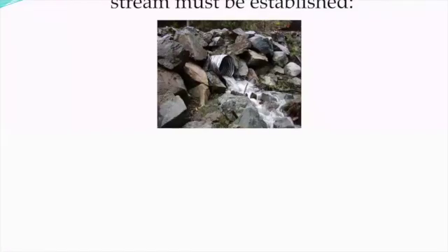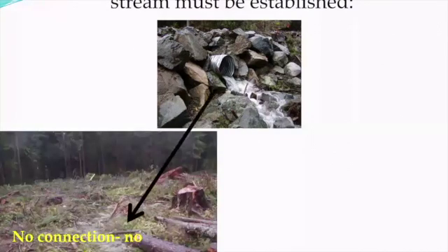So now you've collected the sediment and you're moving it, channeling it downslope. Then you have to say, well, what are the options to deal with that discharged water? I could send that water onto a big open slash. And if there's 200 meters between the outflow and the stream, you can see the sediment will not reach the creek.